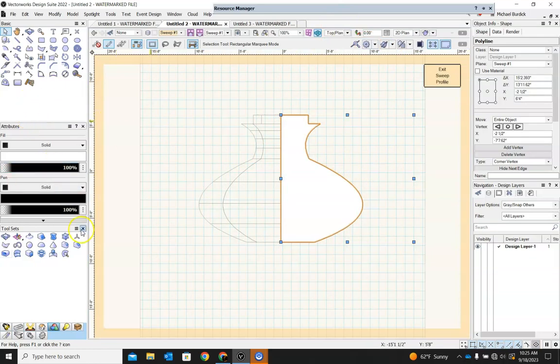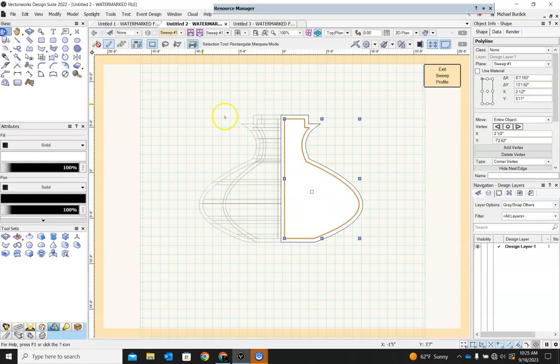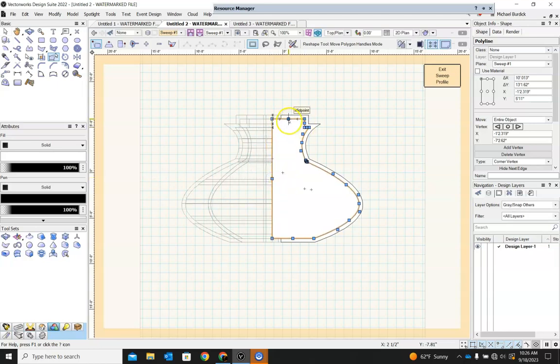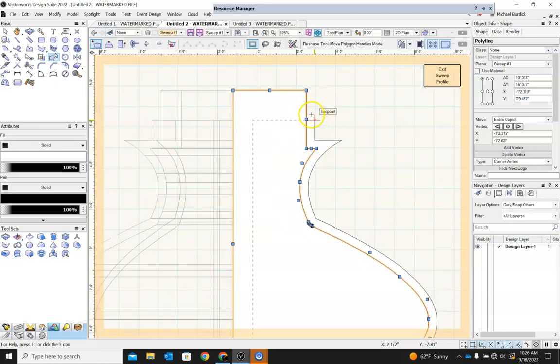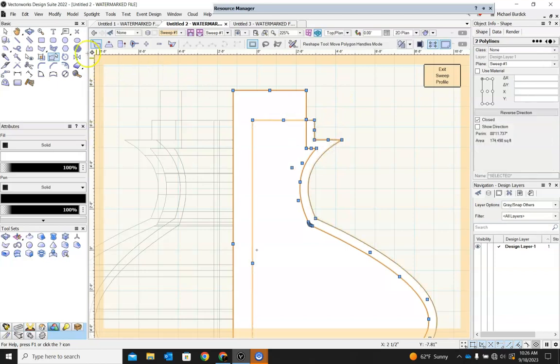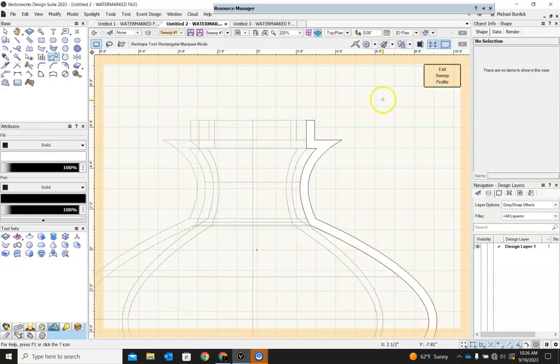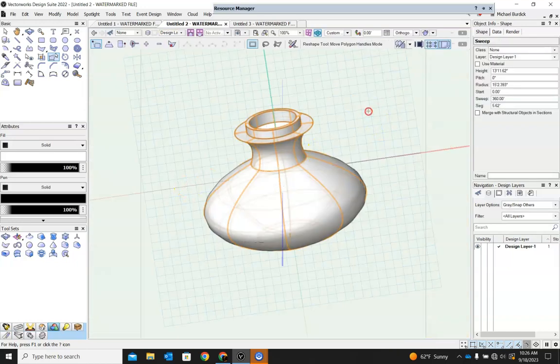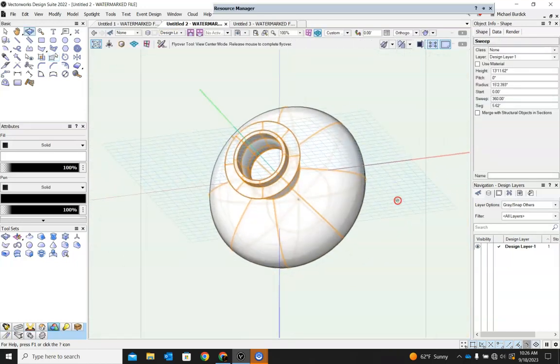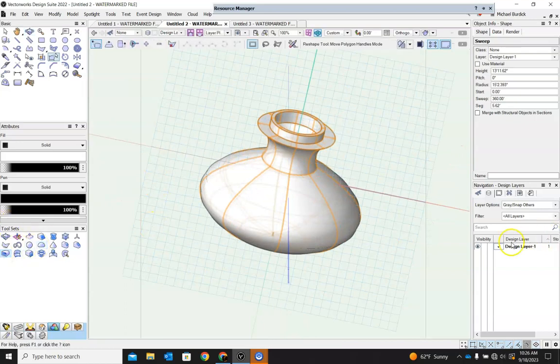So here we are. What we can do is use our offset. Let's bring it in 5 inches, like that. Pull that up. Then I'll just clip these. Get rid of that. There we go. So it's hollow because we changed it on the profile side, as opposed to changing it with the shell solids.